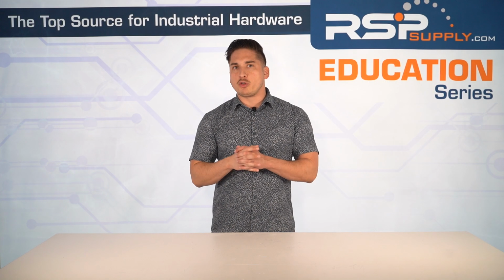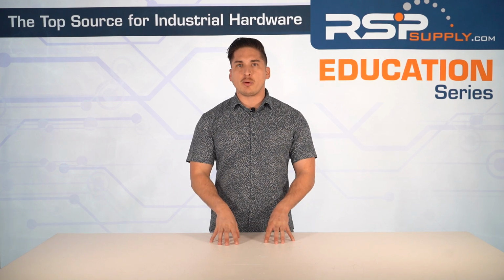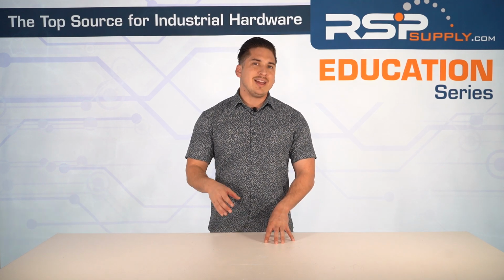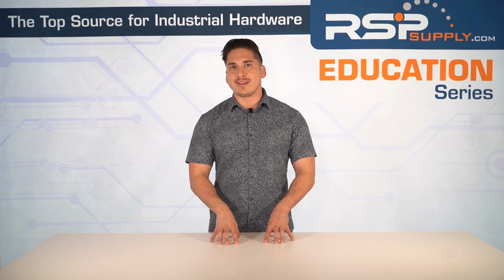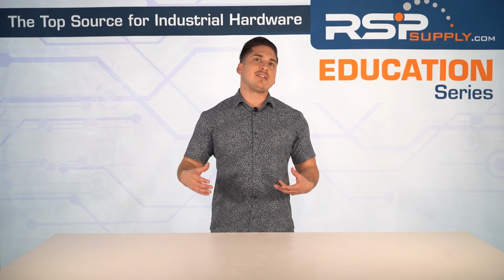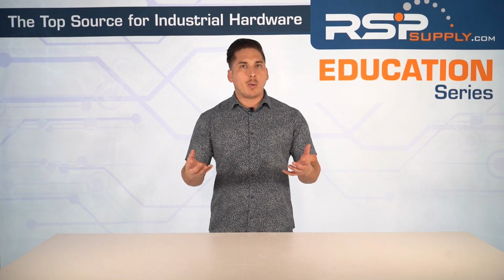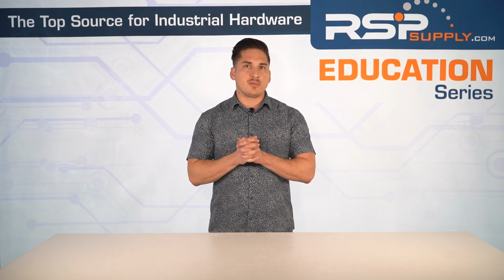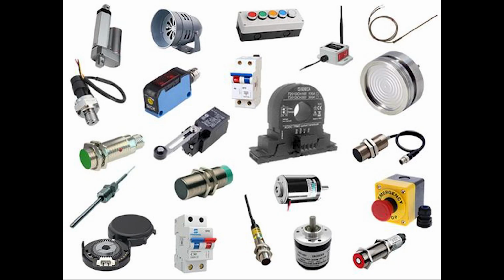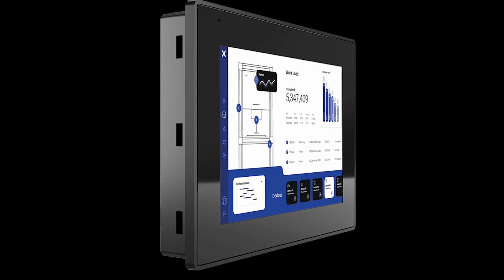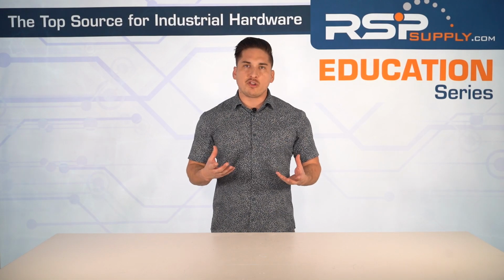So why do we need to rectify AC power in the first place? Most of the electrical power that's generated and transmitted around the world is in the form of AC. This is because AC is more efficient for long-distance transmission and can be easily stepped up or down in voltage using transformers. However, many electronic devices and systems still require DC power to operate, like PLCs, sensors, actuators, HMIs, which are human-machine interfaces.